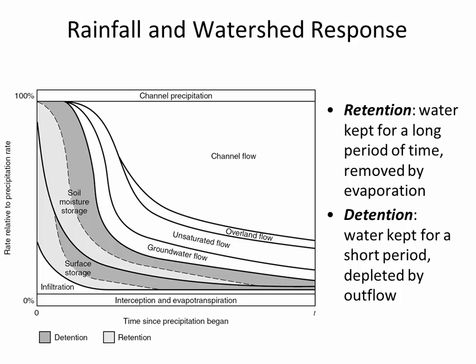And in this diagram, what they're showing is that the infiltration rate never was as high as the precipitation rate. You know, if precipitation rate is 100%, if it was initially raining 1 inch per hour, it looks like the infiltration rate at the beginning at best was only maybe around 20%. So where did the rest of the water go if it's not going underground?